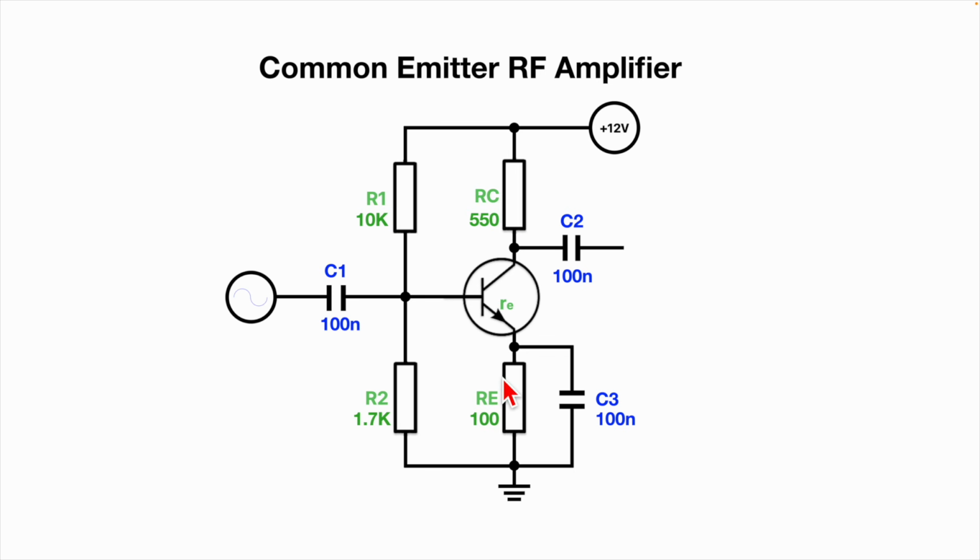This is very similar. This is setting the current. So I've got 10 milliamps basically going through the collector circuit. Notice we are fully bypassing this emitter resistor, which will increase the gain but won't upset the DC biasing. The only real change is in the voltage divider biasing.